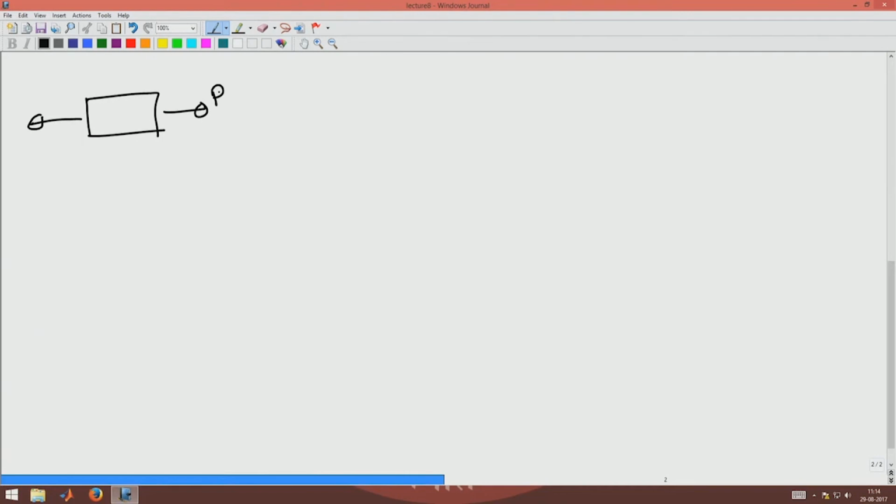I am applying a force P. Let me assume that this force is uniformly distributed over the side. Hence, if I take this as Ex, Ey, the stress state of the cube would be uniaxial stress sigma xx acting like that, and the other components are 0.